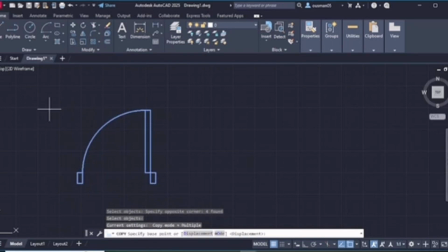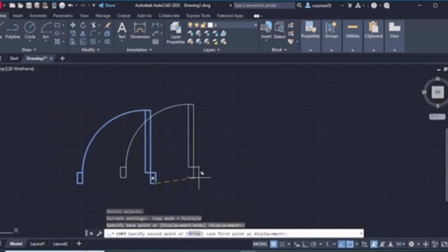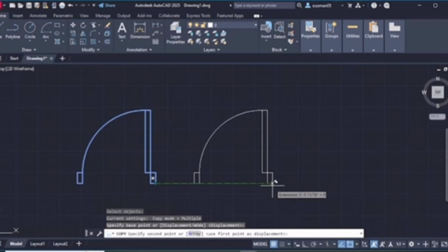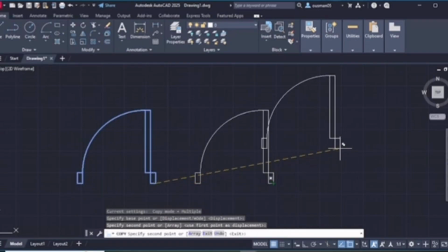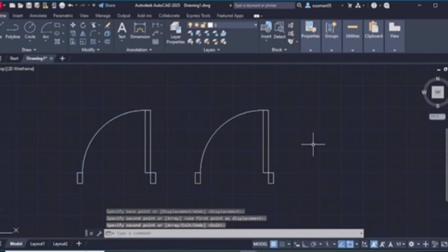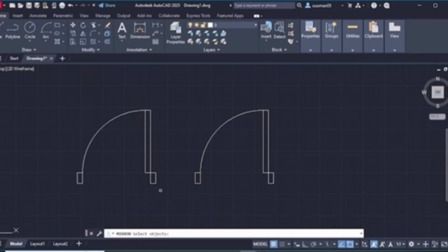This is my base plane. Then I'll copy it like this. So this is this other single door, and this is what I will use to create my double door. So that to easily draw that, I will mirror it. So I'll select this. Before drawing again, just mirror it.